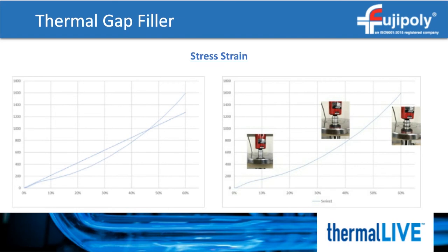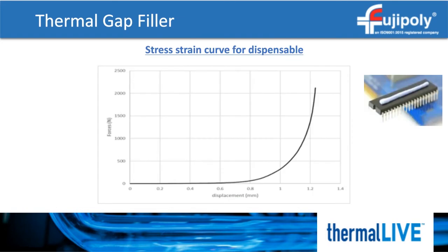Previously, we mentioned that form-in-place gap fillers are very popular because they do not create too much stress. They are a great option for very sensitive devices or assemblies that require very low stress. The stress created by a form-in-place is often negligible. They are polymer-based, usually silicone or some other synthetic polymer base, but they are not cross-linked or have very little cross-linking, so they have no tensile strength. The viscosity is what basically holds everything together. They will easily flow as they are compressed, but even these materials are going to have their limits.